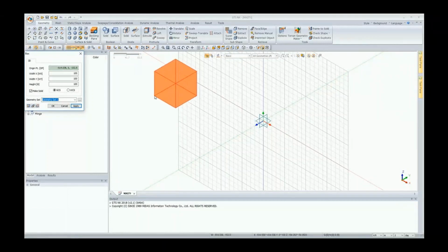The first thing it's going to ask me is the coordinates of the bottom left corner. I'm going to type in -25 in the x, 0 in the y, and -60 for the z. That's the location of the bottom left. Then my width in x will be 50 meters, and the y will be 45, which is actually the length of the excavation. And then the height or the depth will be 60 meters. Then I give this geometry a name, called terrain.